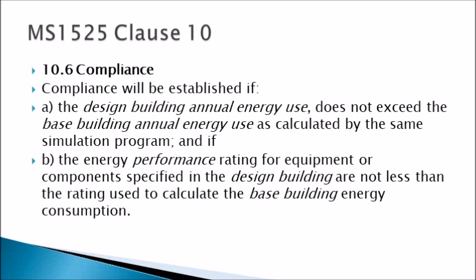That means another condition is that the equipment, for example, the energy level of your air conditioning, of your chillers, the machine that produces cool air or water. There are energy levels, for example, 3-star, 4-star, or 5-star rating. You cannot use something that is less energy efficient than the one you use in your hypothetical shoebox building simulation. So if you meet these two requirements, then you have shown compliance.